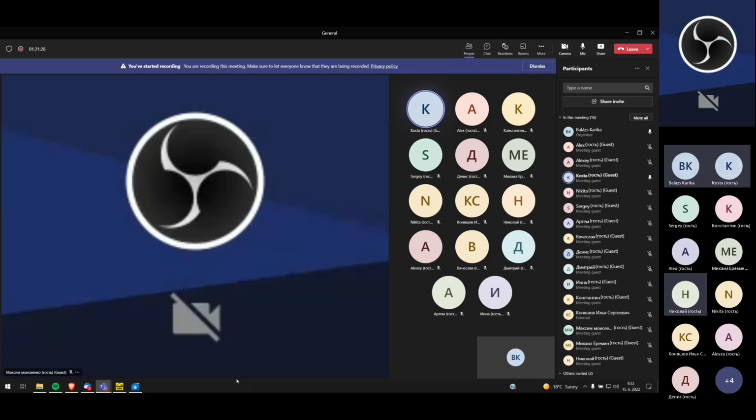In Contras, every truss is cut piece by piece, so there is no combination between the trusses. Like you have an option to cut for all these trusses together, and the program is optimizing. So this is not possible with the Randek, what Contras is using.